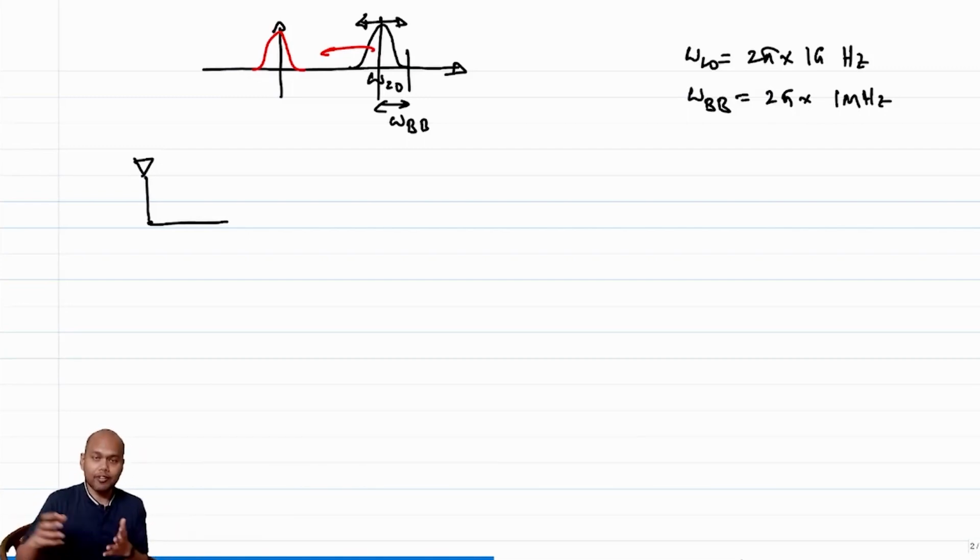And note that ultimately everything has to be digitized, because things are stored in a digital format. So it is always better to have a signal which has a limited bandwidth before I feed it to an ADC, because the ADC otherwise has to operate with a very high frequency clock, right? Okay, fine. Those are very system level information. If you are not following me at this point of time, don't bother. As the course progresses, things will become clearer and clearer. Okay, fine. So let's proceed.